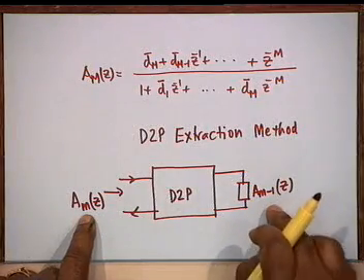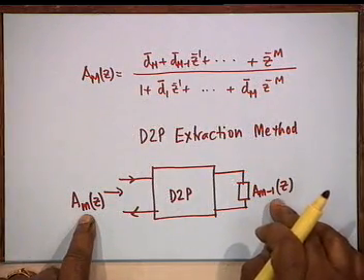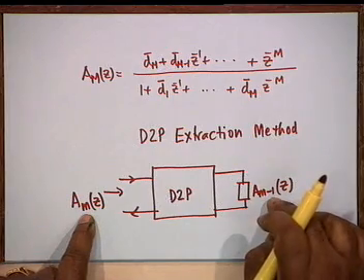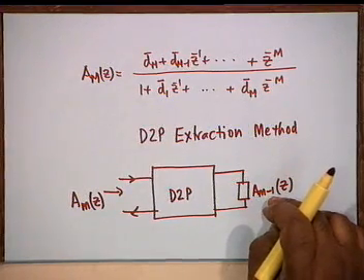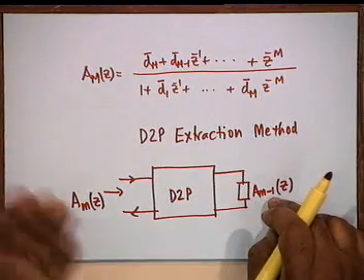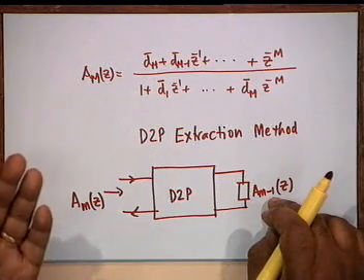What will be the last? Now we have to show that at every stage we shall get an all pass. At every stage, that is A_m(z), when we realize it as a termination of A_{m-1}(z), we shall have to make sure that this is all pass. And we already know a procedure, don't we? In IIR stability analysis, stability testing, we know a procedure.